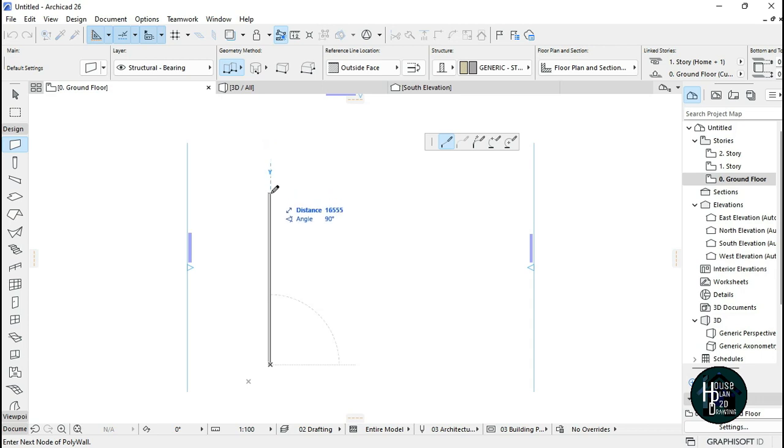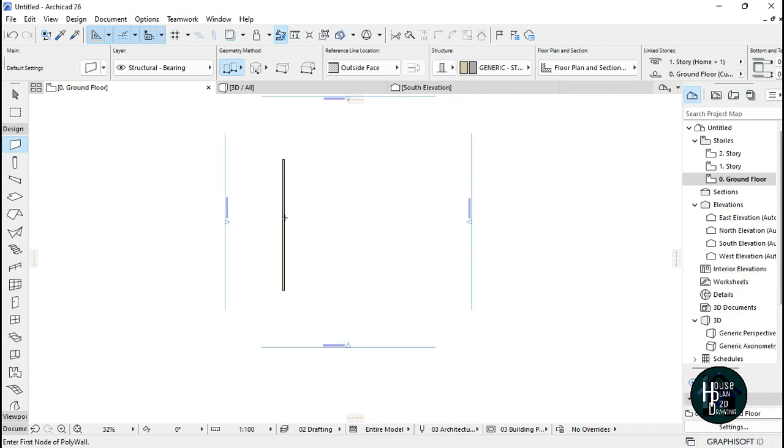As the distance is reading, you can click anywhere, or you can type the figure you want the dimension of the fence to stop at. So I'm going to write 17,871, then click enter and click enter again. As you can see, this is the length.